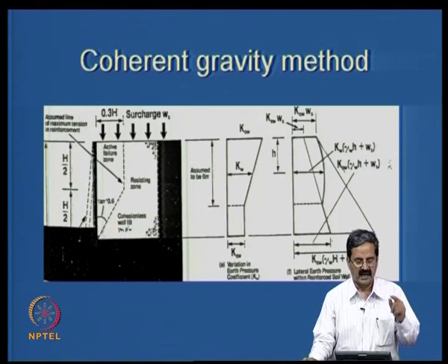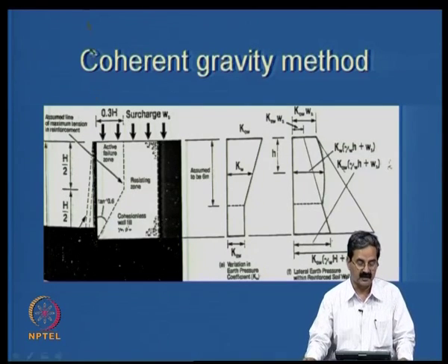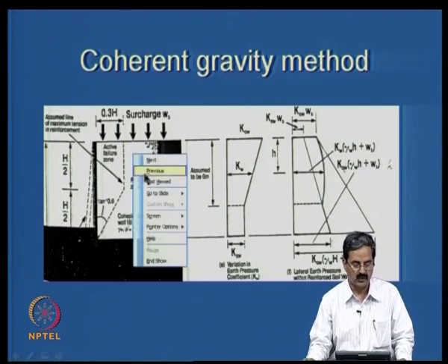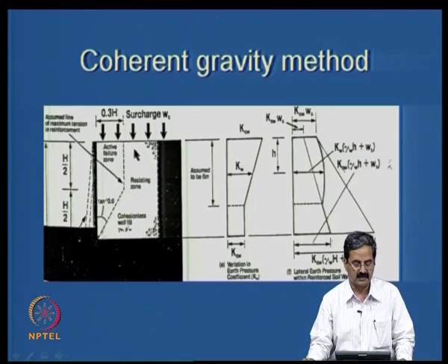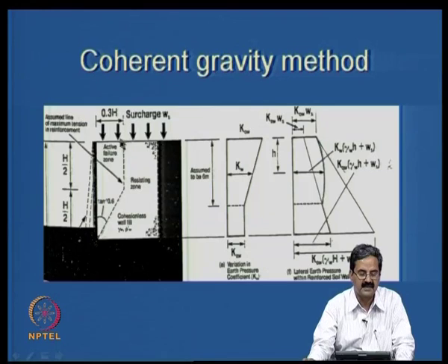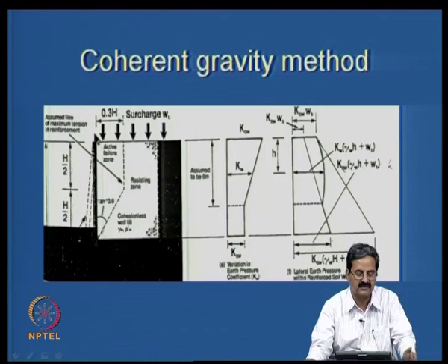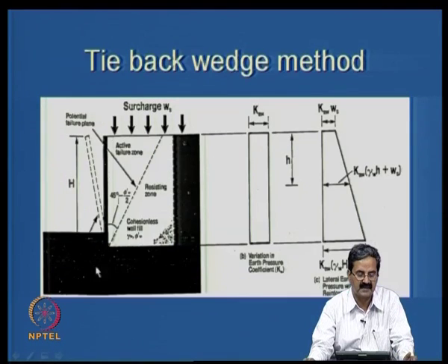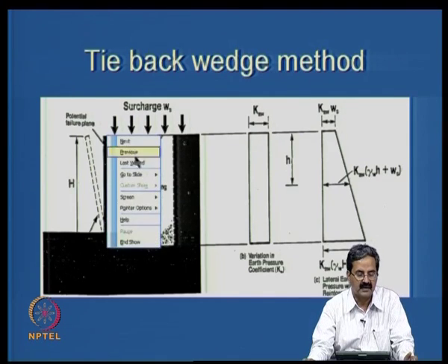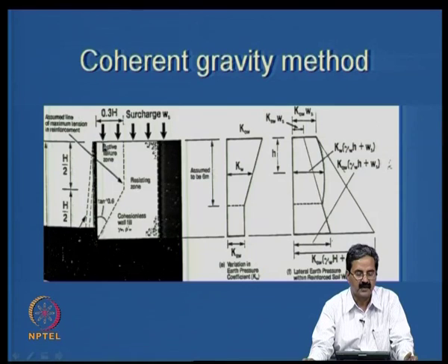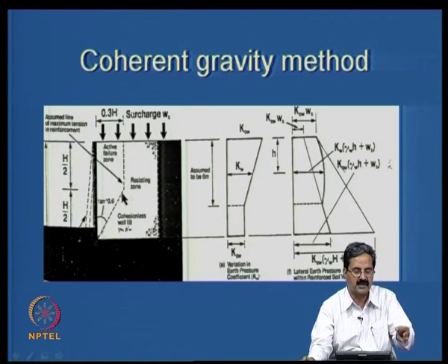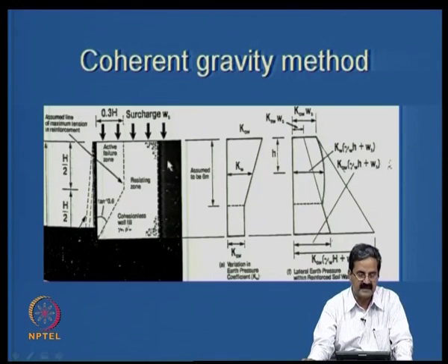We have seen that. Whereas a geotextile is a flexible reinforcement, it needs some strain. So I can't assume this sort of distribution. I should only go for the previous distribution. In this distribution, what people have observed is that it also rotates about this point. In the other case it was somewhat reverse. Like you can see in the previous case, the rotation is about the toe, whereas here the rotation is at the top. So that's the assumption that they have, and they have measured actually. They have measured the earth pressures, and then even measured the strains.